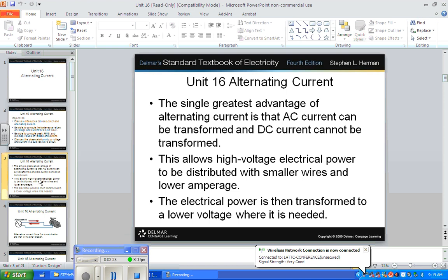You can buy a UPS system for your computer at home. It's just got a little battery that takes in AC, converts it to DC, and lets your computer run on the AC that's inverted from the battery. So it's AC, then it becomes DC, and then it becomes AC again, all in one little system. And that's the way they all work.